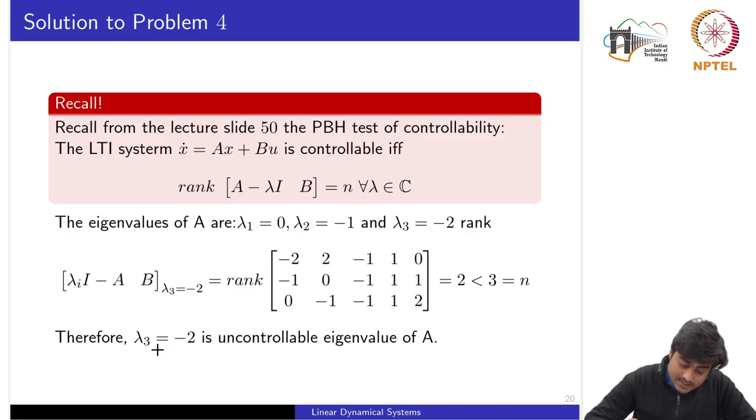Okay, because the stabilizability test speaks only about the eigenvalues which are on the right hand side. Here, the eigenvalues for which it becomes uncontrollable are on the left hand side. So without even doing further tests, we can say that this system is at least stabilizable.